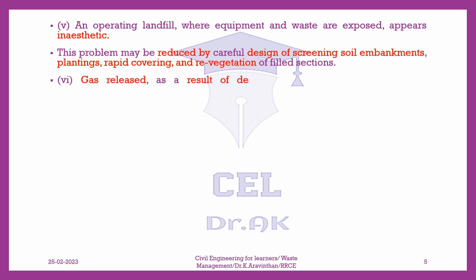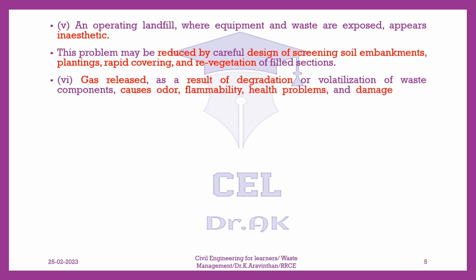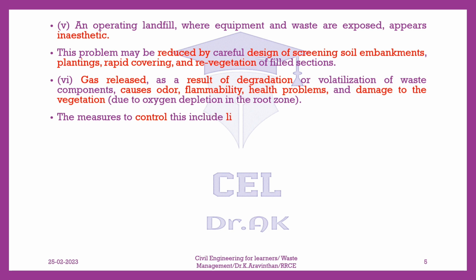6. Gas released, as a result of degradation or volatilization of waste components, causes odor, flammability, health problems and damage to the vegetation, due to oxygen depletion in the root zone. The measures to control this include liners, soil covers, passive venting or active extraction of gas for treatment before discharge into the atmosphere.